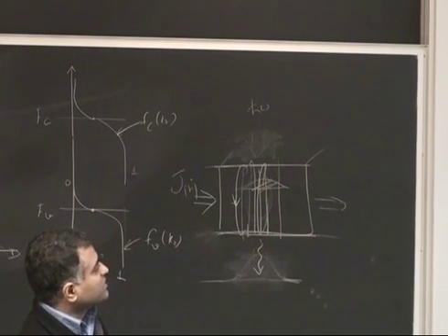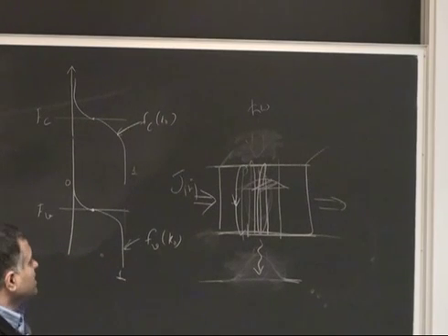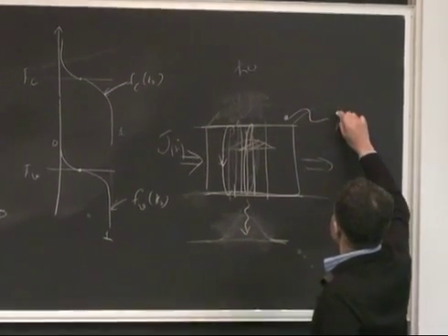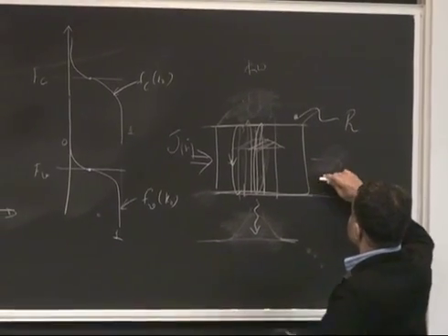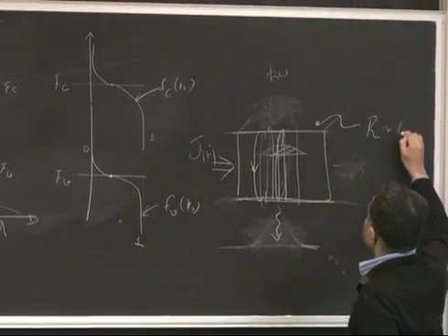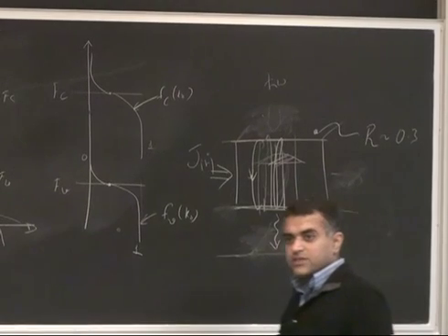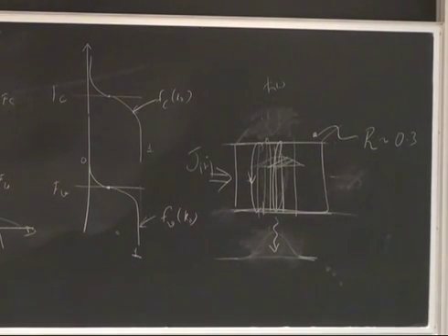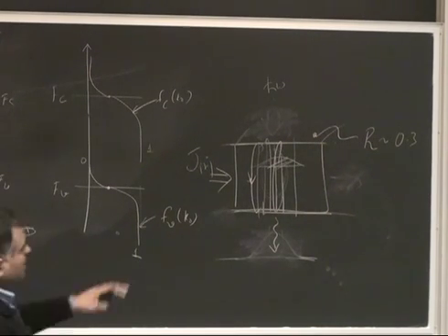so as you can see, the quantum well emitter. So all the details inside. Let me just give you a rough rule of thumb. What is the reflectivity of an edge emitting cleaved edge? It's actually rather low. It's like 0.3, 30% reflectivity. Okay. So there's quite a bit of light leakage in these structures, but I think that even after all this, the net efficiency can be very good. I mean, because the material quality can be improved, the loss can be lowered, and all that kind of stuff. So there, for a cleaved edge.